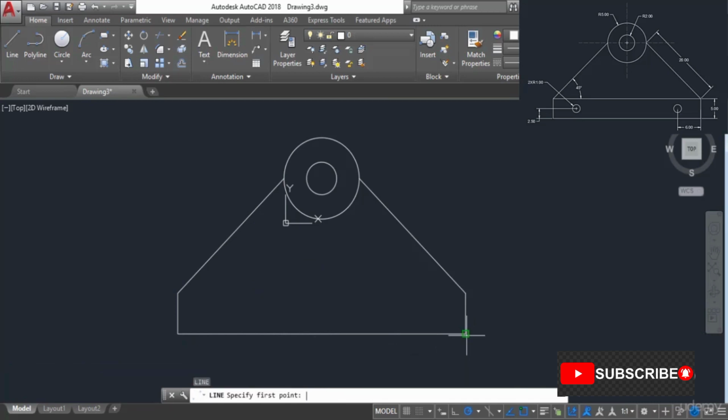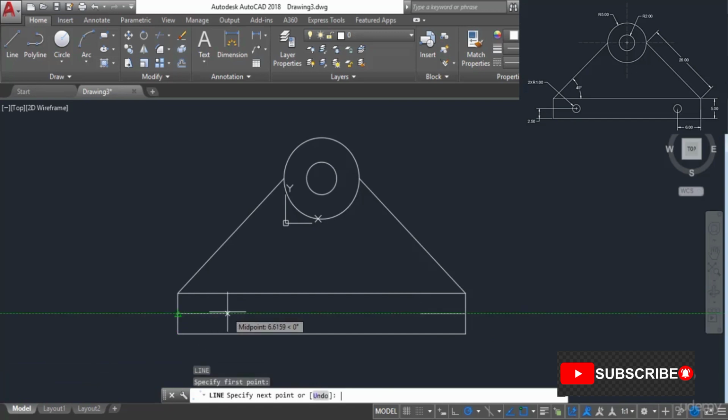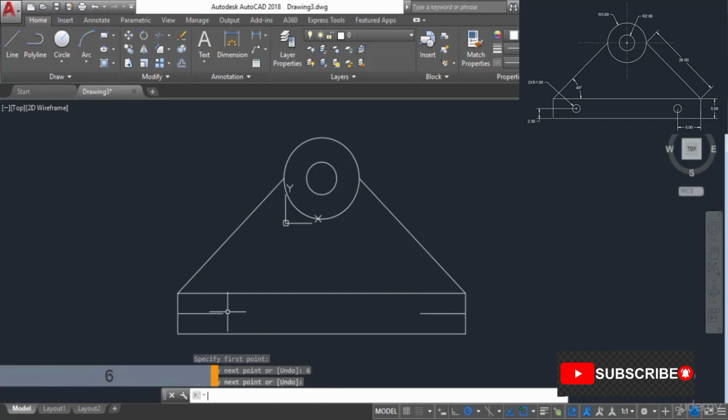Now press enter again to repeat the line tool and join these 2 points. There we have it. Now we only need to add these 2 small circles, the circles which were here and here. In order to do that, I'll start with line and click at a point, move it in the left direction, enter the length 6 and press enter. Press enter again to exit it, and press enter again to start it. Now click at this point and make another line with length 6 and press enter twice.